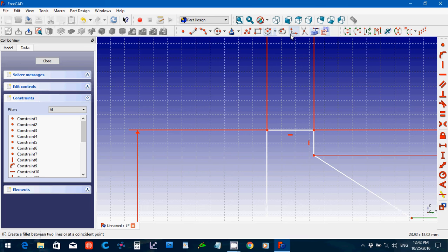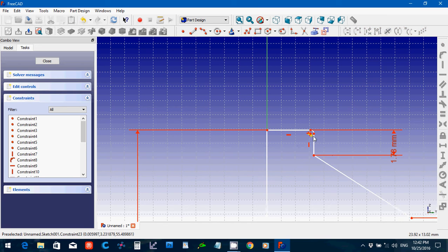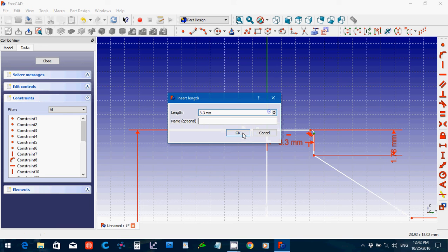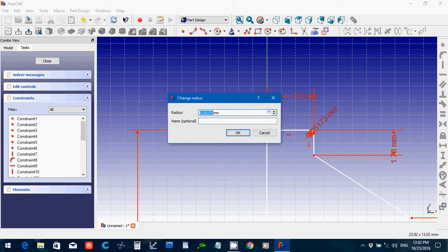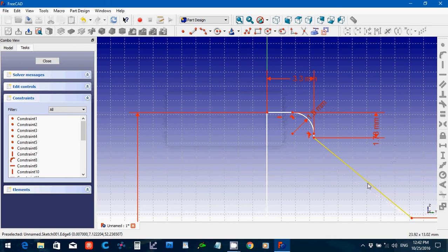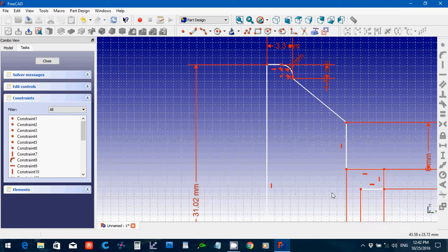Going to fillet this corner. Let's go ahead and set those dimensions back to where they were, so that I don't change the... But I'm going to want to change the fillet. Let's see, 1.5. Okay.